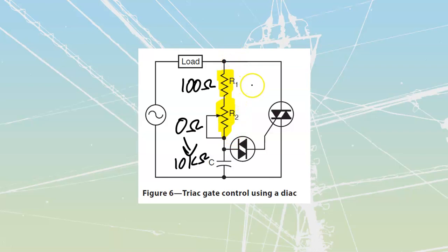It's just a really handy thing for us to have. So we'll commonly see a fixed resistor in line with the rheostat, so that the customer cannot drop below certain levels. We'll do that even in industrial controls. When you get into PLCs and things like that that are control devices, sometimes you're going to use rheostats that give you a 0 to 10 volt signal back, or you can be running a 4 to 20 milliamp.